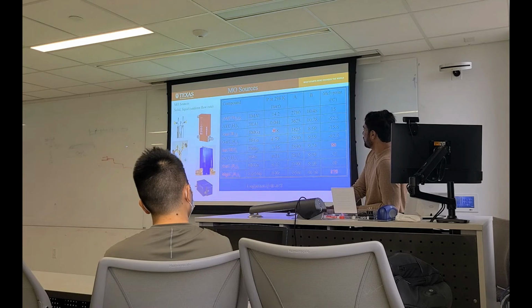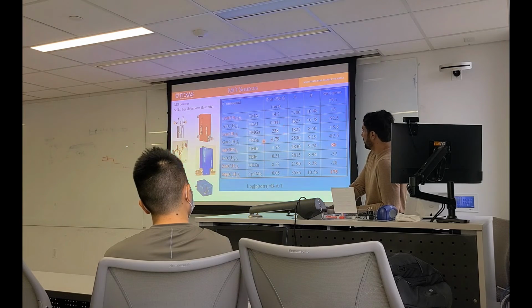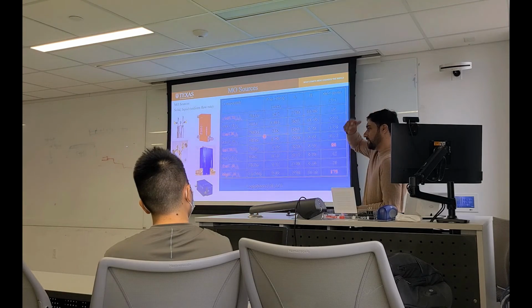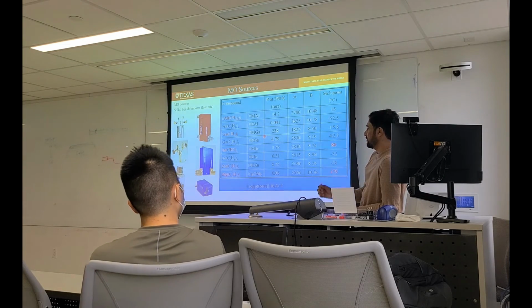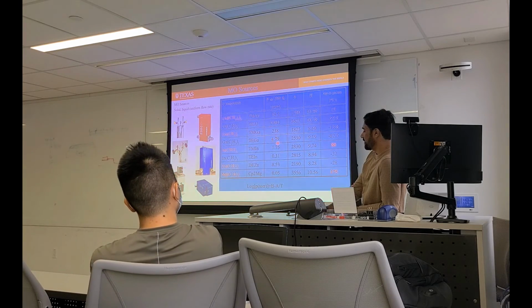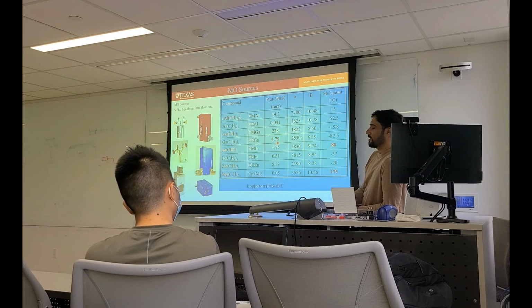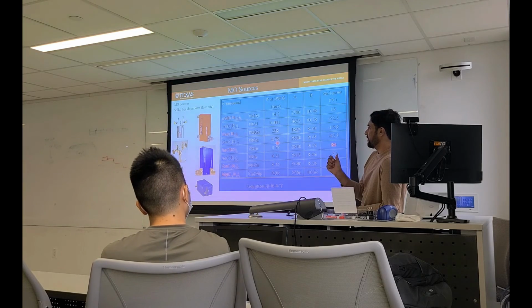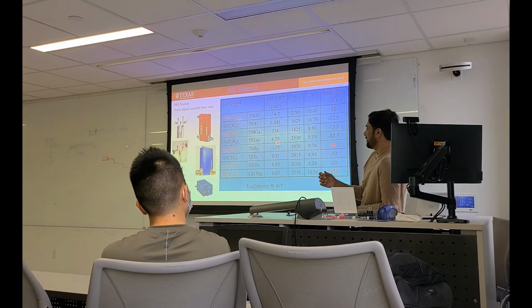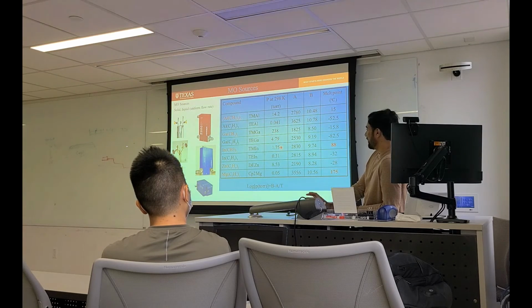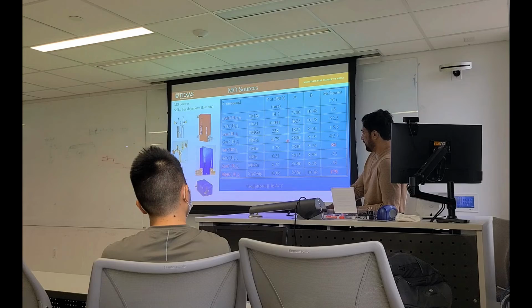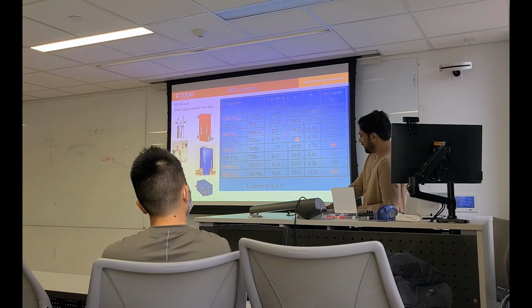So you see, this is 238 at room temperature, 298, and this is 4.79. It is very low, and you need a bigger mass flow controller for this one, because you need to increase its bubbler pressure. We can increase it by heating at high temperature, and we can also control the bubbler pressure with an electronic pressure controller. But still, whatever we do, it will give a lower growth rate, because 238 is very high compared to the other. So that is the case where it gives the lower growth rate, but crystal quality is better.